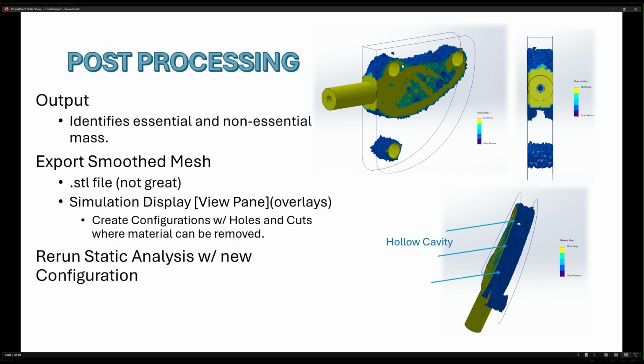And we're going to essentially use that optimization feature and connect it to this bottom pin as well, and kind of use that design language in our part. But the way you can do that is you can either just take an STL and smooth it out, make it printable. You can just throw it into your slicing software, or you can overlay this part onto yours, and then it's basically like a ghost. It's opaque, and trim away as needed.